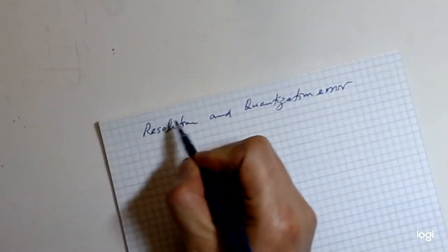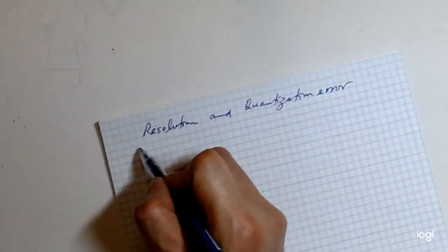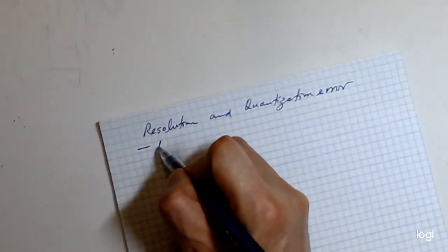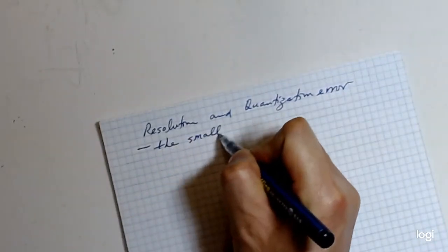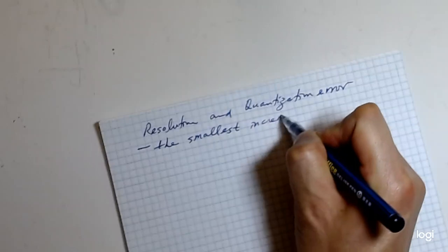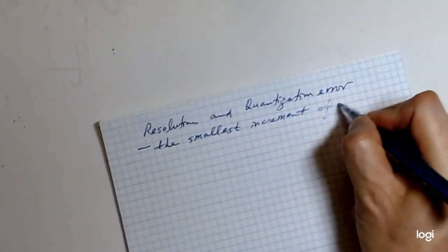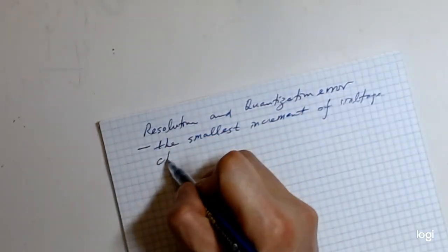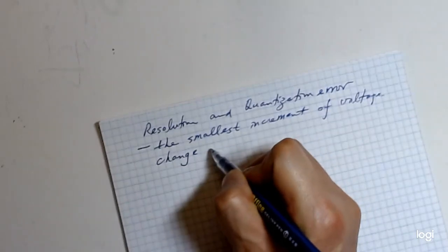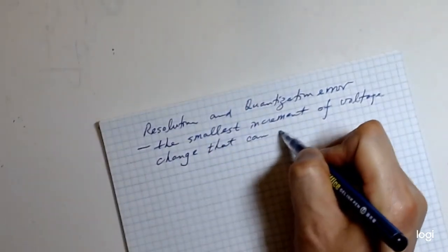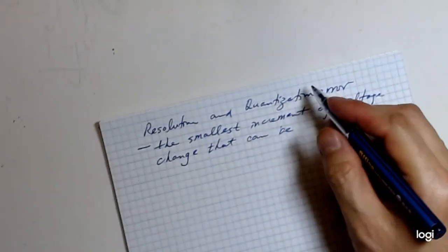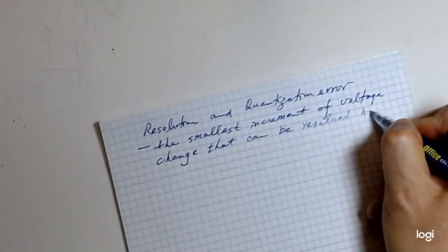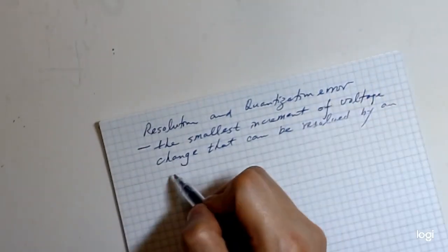So what's resolution? Resolution is in terms of the y-axis, that's voltage, that's amplitude. Same definition as before: the smallest increment of voltage change that can be resolved by an AD converter.